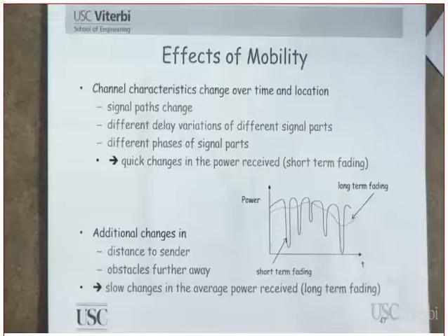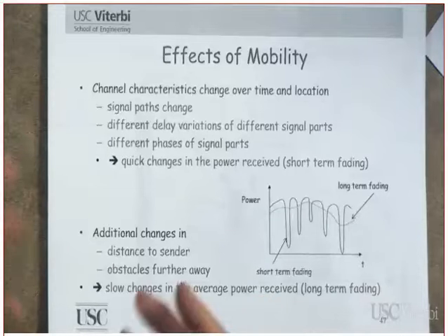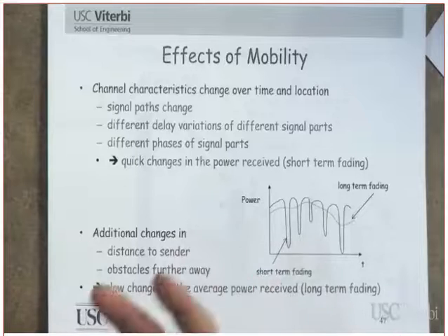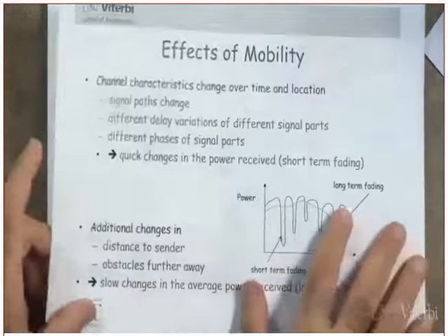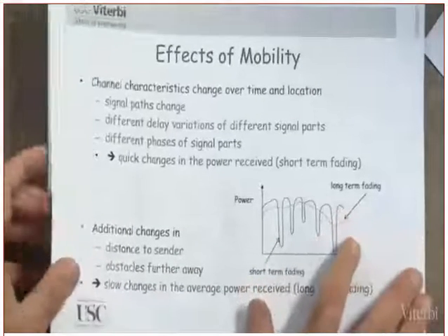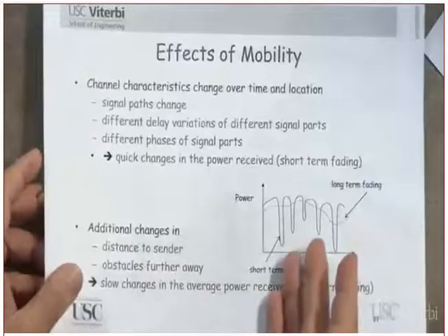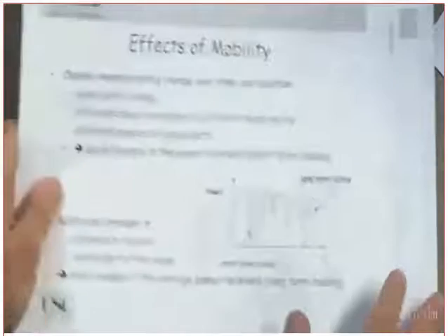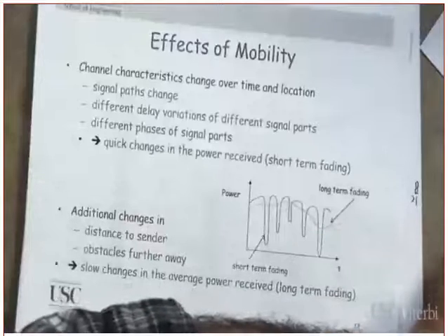Clear? Now you might say, what difference does it make if you transmit them multiple times? Remember what I told you a moment ago: the channel is time varying. Maybe during that time it's not good, during the other time it's good. You could also have spatial diversity by including multiple antennas separated by a certain number of wavelengths, such that you make the received signal add in a constructive way rather than in a destructive one. You will learn this one in 535. Clear? We don't get into diversity in this class. We don't have time. I just brought it to your attention so that if you take the class, it will help you.